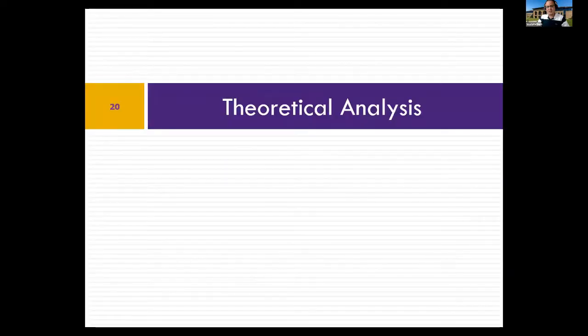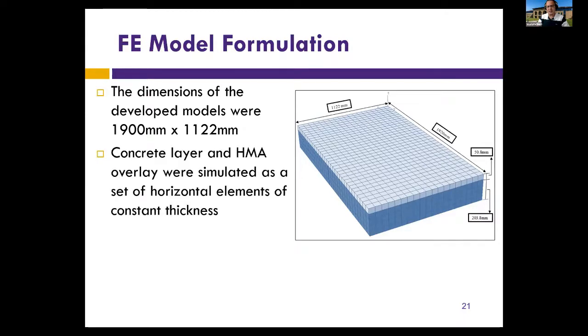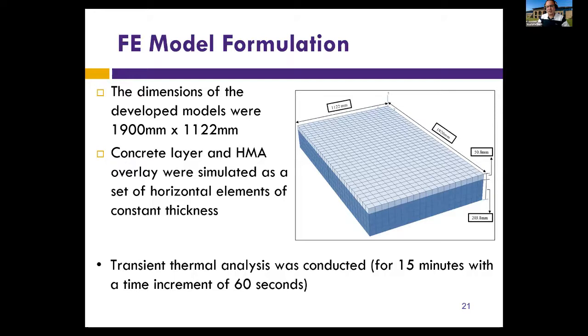We complemented this result with finite element analysis. We developed a thermally transient analysis using finite elements, and we simulated exactly what we had in the field. We had a concrete layer, and on top of it, we had an asphalt overlay being placed. We conducted the analysis for 15 minutes. Basically, you start with the hot paving mat, and the paving mat keeps on cooling over time. And we studied the location at the joint and away from the joint.